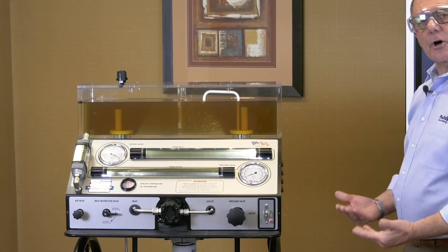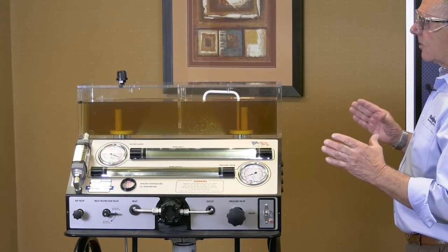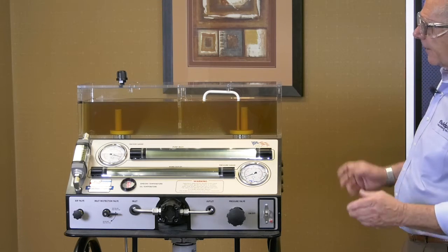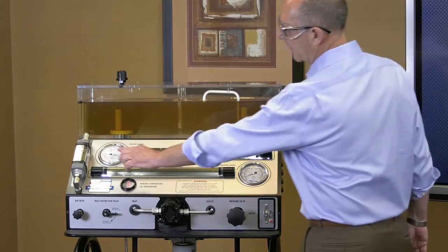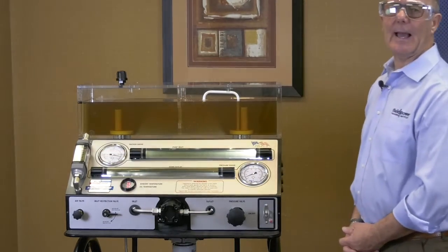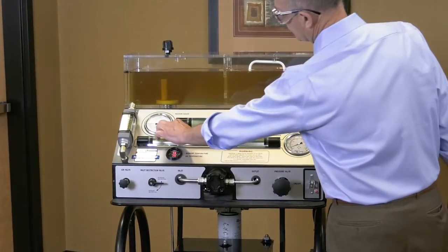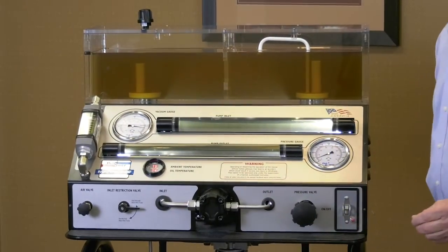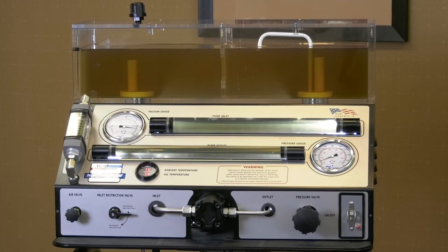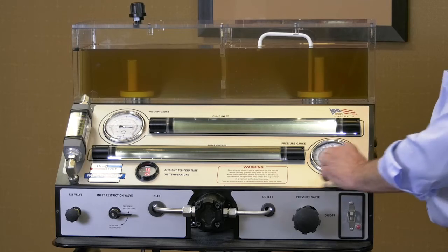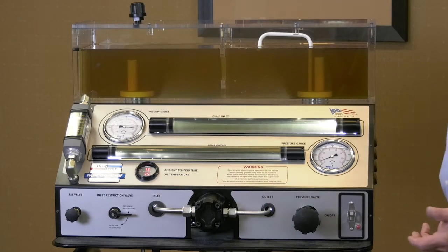And let's look at what the normal operating parameters of this hydraulic system are. What are they? Well, first of all, if I start here, I've got 1.8 gallons per minute. That's my pump's flow rate. Next, my inlet restriction is 4 inches of mercury. Pressure is nominal or low right now. My ambient temperature is 75 degrees Fahrenheit, and my oil temperature is also 75 degrees Fahrenheit.